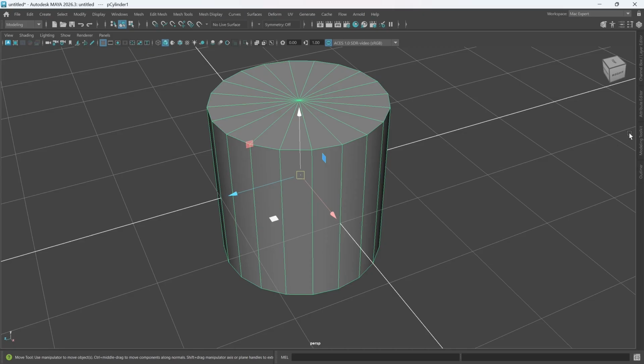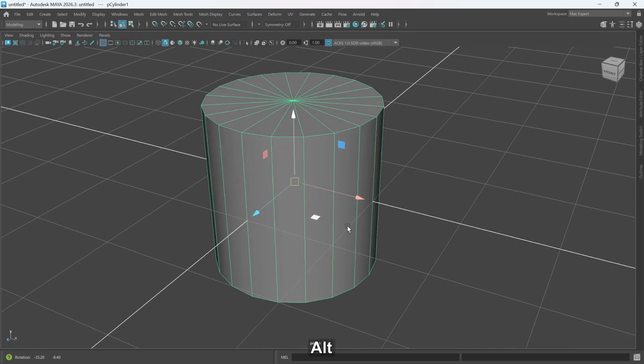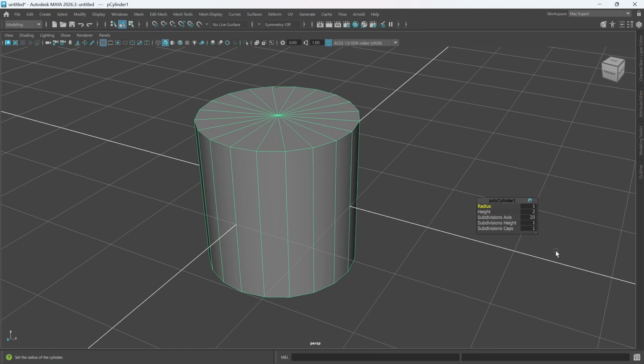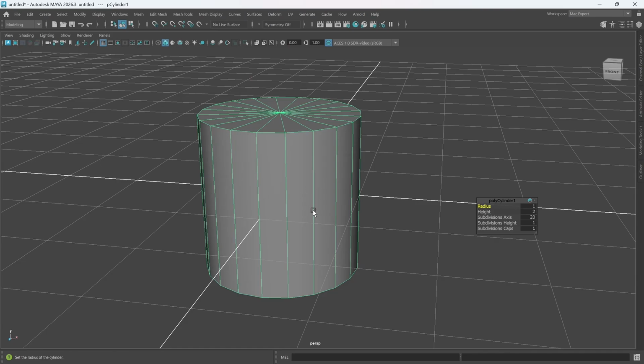Now you can go into the attribute editor, but we are going to learn some shortcuts and some advanced techniques we can use to speed up our modeling in Maya. Now, when you just create a shape, if you have not modified that shape, like modifying the components such as the face, the vertex, and the edge, when you hit the T key on your keyboard, it is going to bring out the properties of that particular shape you have added to your scene.